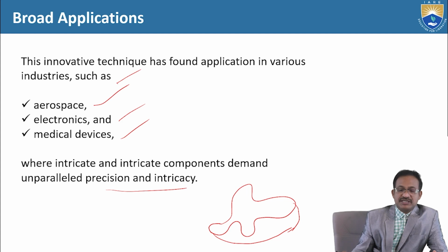Through conventional machining processes, it is very difficult to cut this kind of complex profile. But with laser beam machining, if we have any kind of path, the laser tool can travel over that path and cut the material line by line or point by point.